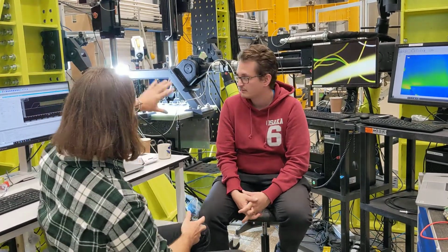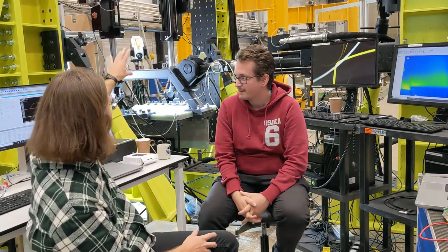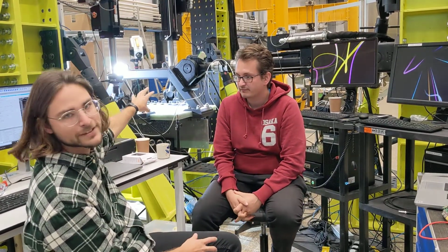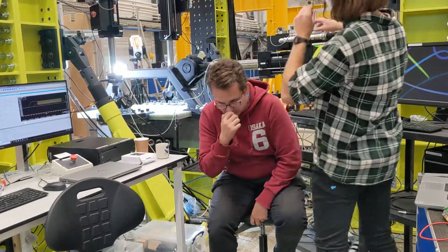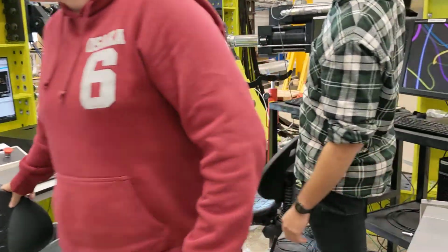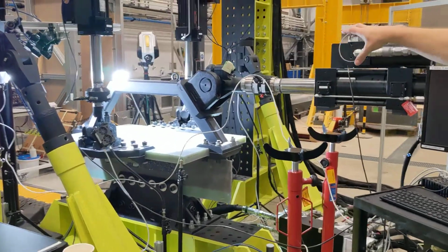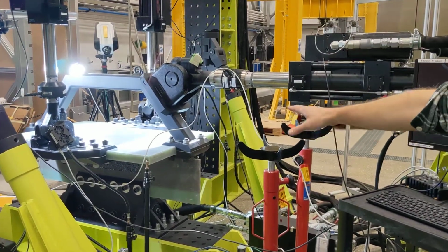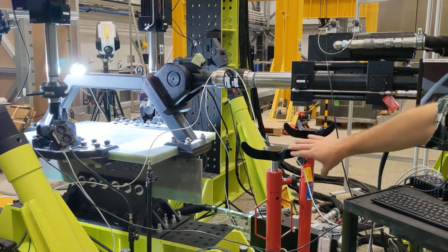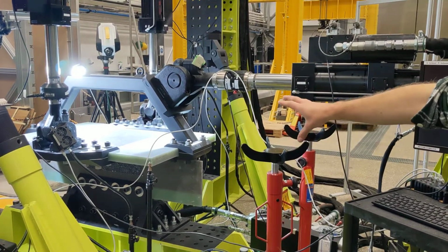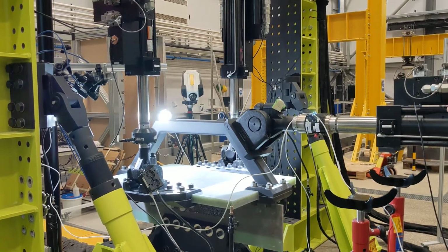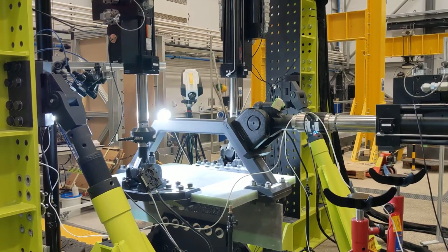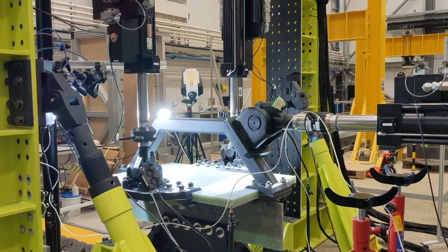And so we are running here this multi-axial test, which is part of a wind turbine blade. Basically, we have a horizontal actuator that induces shear load into the web, the vertical part of this three-dimensional T-joint. And then we have two vertical actuators that induce cross-sectional deformations into this test piece.